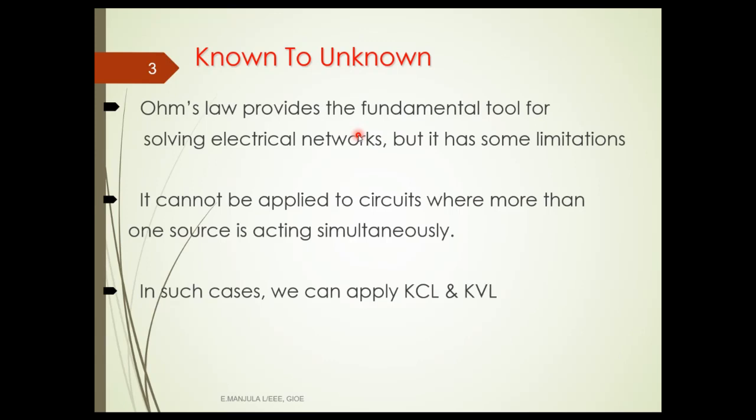It is used only for fundamental networks, and it cannot be applied to circuits where more than one source is acting simultaneously. Where there are two, three or more sources, Ohm's law cannot be applied. In such cases we apply KVL and KCL. We have solved problems on KVL and KCL also. Then when we can use the superposition theorem, we will see.